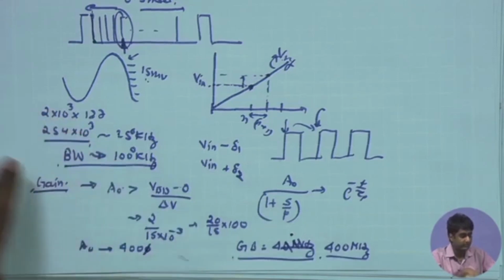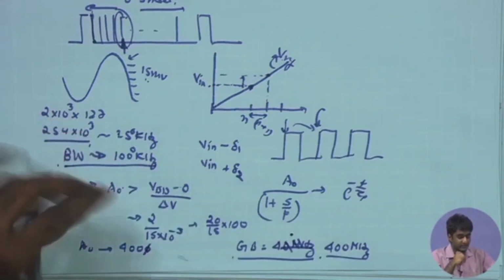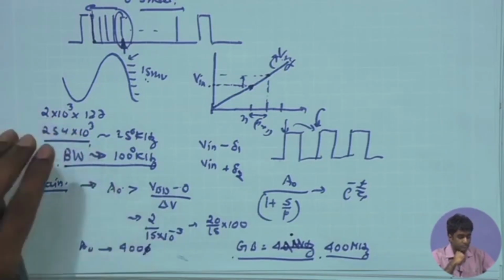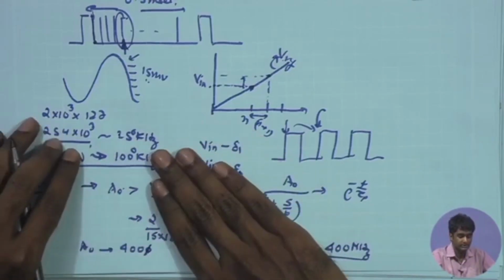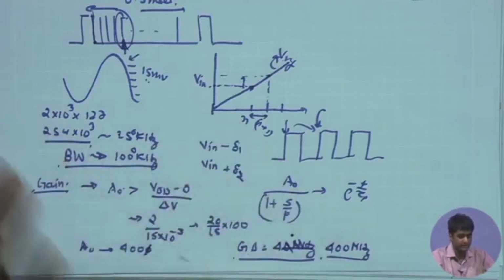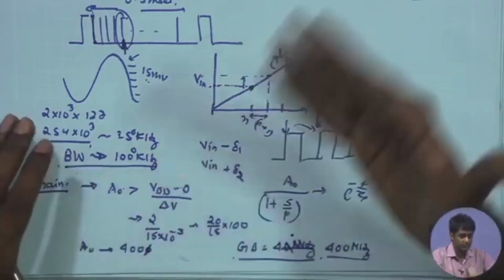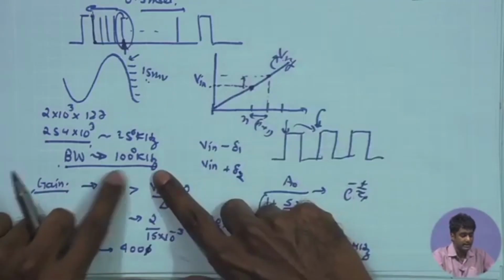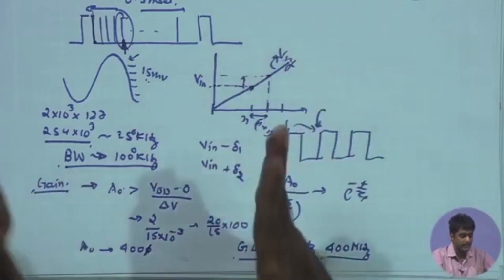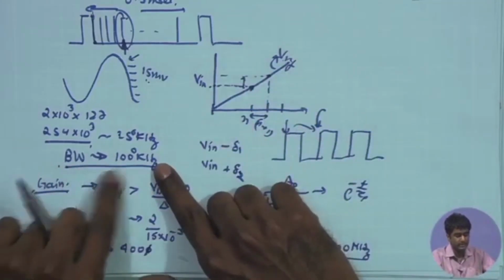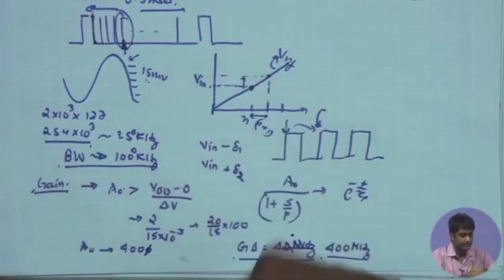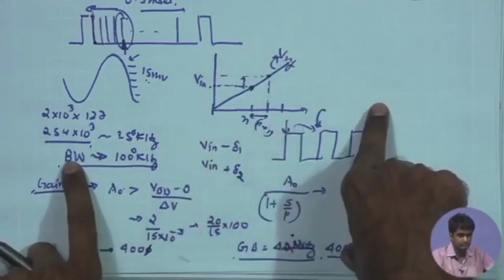Here intentionally I have increased the bandwidth from say hundreds of hertz to a kilohertz. In our earlier discussion, the bandwidth of the signal was maintained within 100, but just to ensure that the higher frequency content is not lost, I have intentionally increased the target bandwidth of the system to be at least 1 kilohertz, and that would mandate a larger bandwidth.